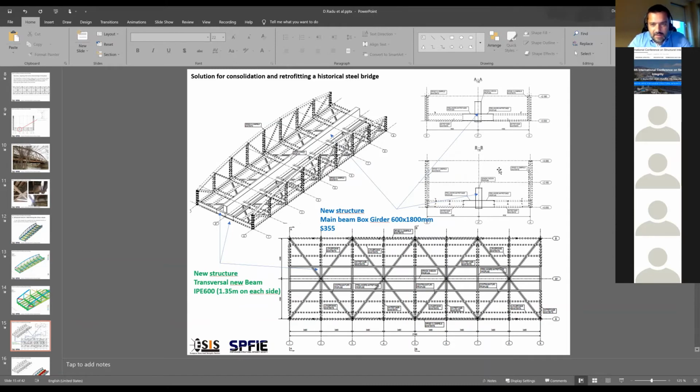So we do have the existing structure that will be cut in half, and in the middle area, it will be erected a beam that will be a carrier beam, a longitudinal one. In this way, it will not be needed a middle support point. So this will be having a good implication of the structural behavior, because it will take almost half of the loading. We will see also in the stresses values.